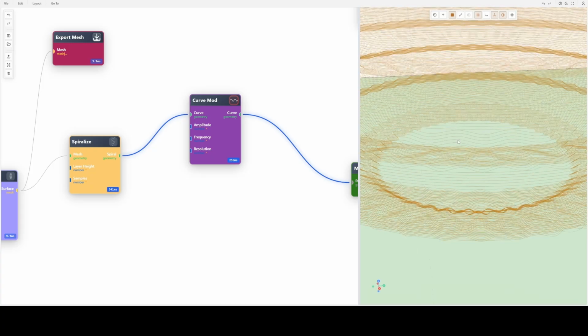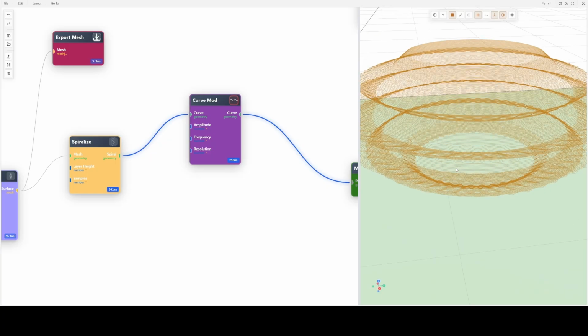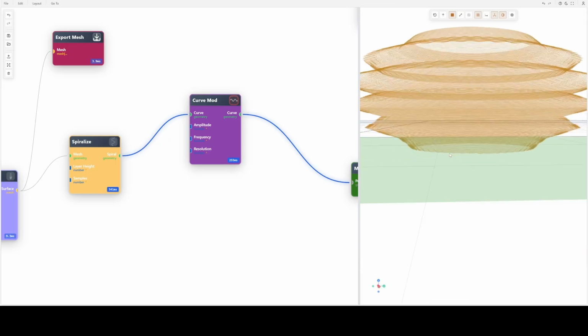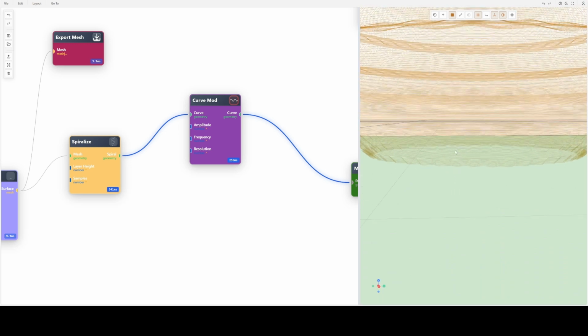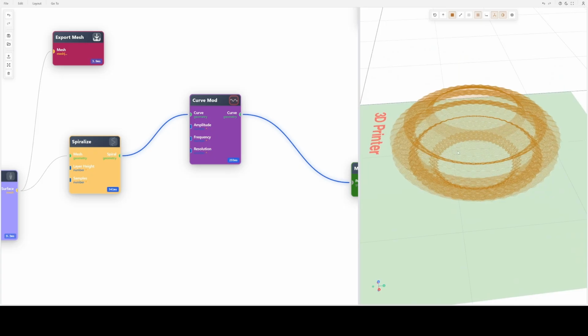So these are useful settings for some situations where you cannot avoid the seam. If you define a skip pattern, it helps a lot to hide the seam in your lamp shape, for example. If you're using this skip setting, in most cases you will not recognize any seam at all. So this is actually quite useful. Okay, you can play with that.